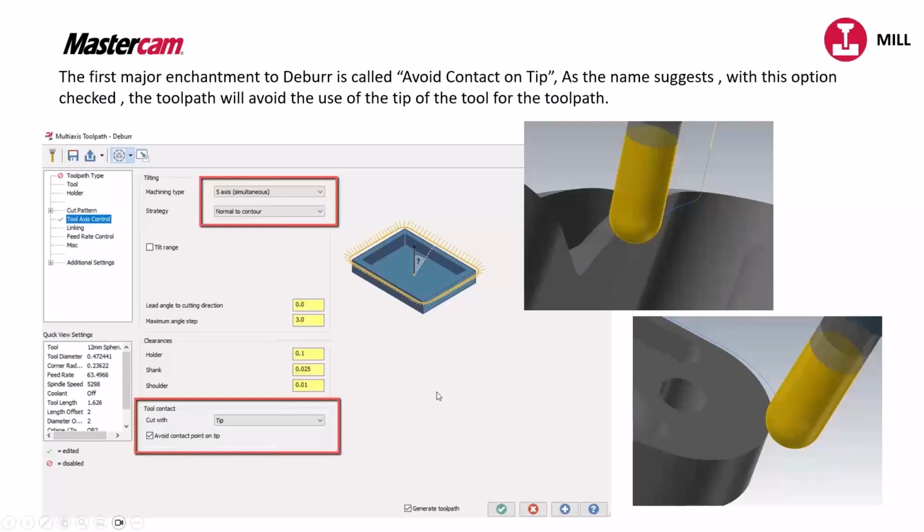And I have a file to sort of show this. But now with 24, they've introduced an option where if you select tip, you can avoid the contact on the tip itself, which makes a difference because at the tip, we all know it's cutting basically at 0 and you're pushing the material out of the way. So now we have this option to avoid the contact on the tip.